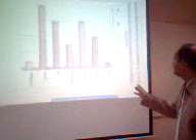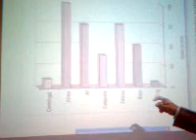Here you can see the share of different yarns. You can see the share of ring yarn is very high, but the production rate is very low. The production rate of ring is the minimum, and you can see vortex spun or jet spun are the highest.